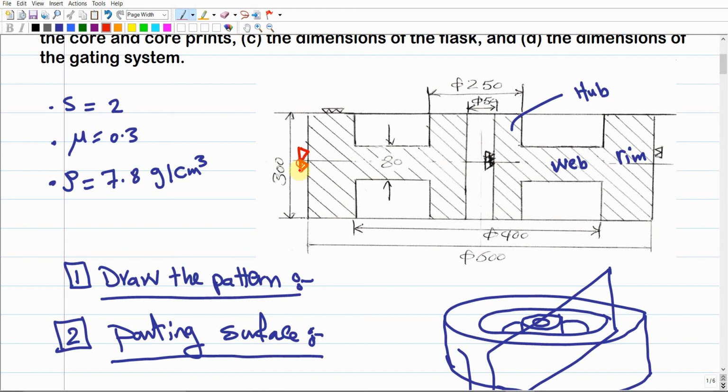But there is no need to redraw the same symbol over the other line, because intuitively the 600 refers to a cylindrical surface and all of the surface should be machined. So you should understand that this symbol should be repeated here. It means that we are going to add machining to both sides, not just one side, right? And the degree of the machining over this surface is second grade. It is not a third grade.